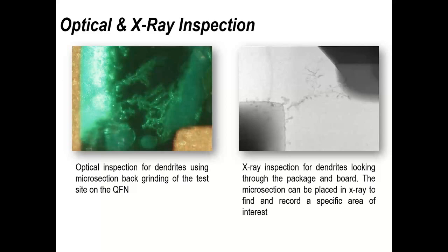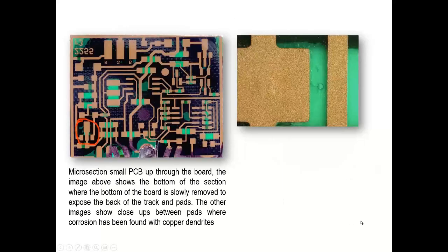So if you were to take that package off, rip it off, rework it off with hot air or whatever, you destroy that information. But with using epoxy to hold the sample in place, again, you can use it in a different way to show up what's actually happening without losing the information. Because in failure analysis, the information is the most important thing, never destroying it if you possibly can. You can cut up the sample, but don't destroy the information if you can retain it. And certainly, you'd photograph it before any step in this operation.